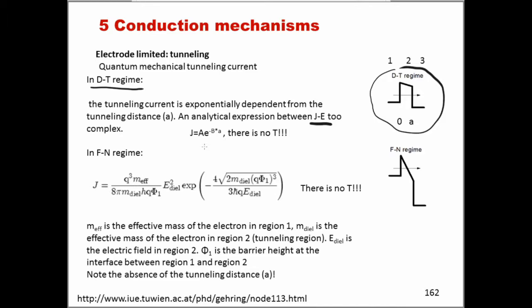But what we can say for sure is that this tunneling current is exponentially dependent on the tunneling distance, and most importantly, there is no temperature dependence. This is a fundamental characteristic that relates to any tunneling phenomena.